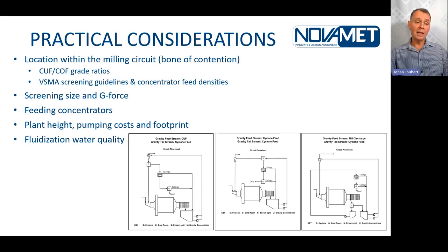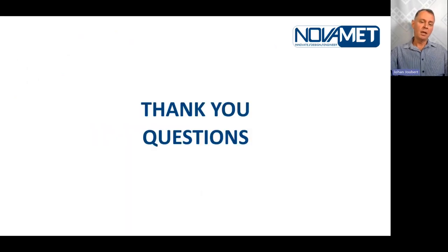I also urge you to put in dedicated fluidization water pumping facilities, and do not rely on the rest of the plant to give the water quality as well as quantity for these units to operate. So that's GRG in a nutshell. Obviously, it's a much bigger topic, and there's much more to learn from it. But assess each project as it goes, and hopefully this was helpful in some way or another.